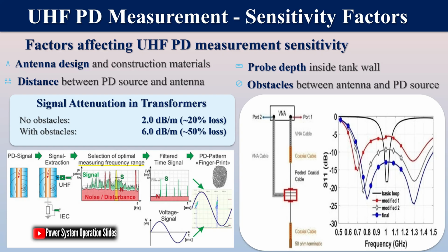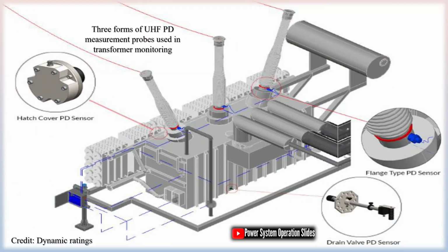of specific fault types. However, conventional methods face significant limitations in field applications, particularly their sensitivity to electrical noise from external sources such as inadequate corona shielding of line terminals, bad or loose connections, PD from other interconnected high-voltage systems, or arcing from transmission lines.